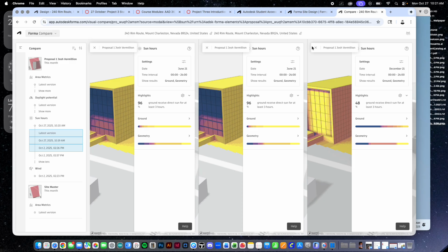It's not that we want to block all the light from the south, it's that we want to screen the heat away from the light. So we need to bounce that direct light at least once before it gets in our building, so that we can start to minimize the heat gain inside, right?